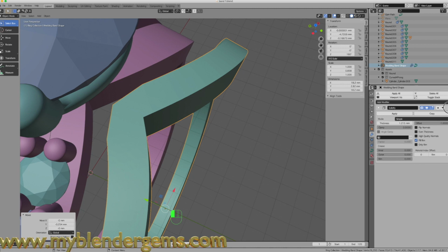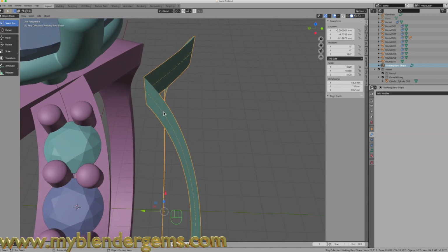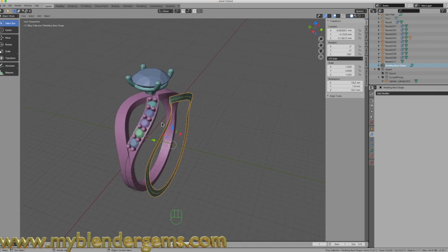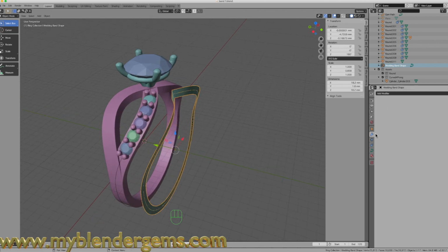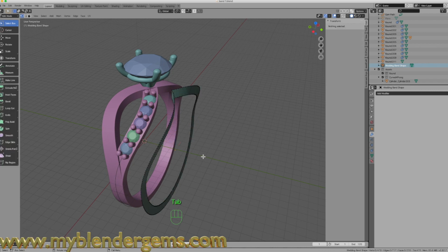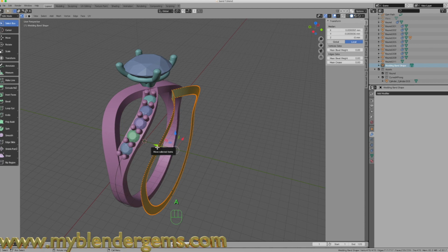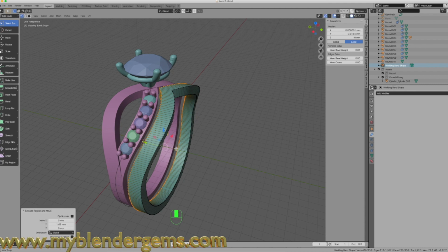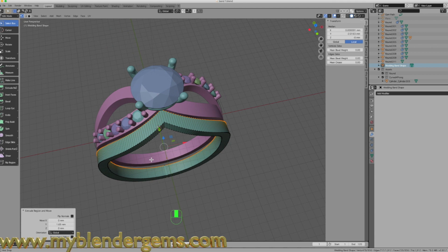If you didn't want to use the solidify modifier, we could convert this to a mesh and also just extrude this to the left or right, and that would be done like this. We take this model, and we don't have any modifiers on it, but we want to convert this over to a mesh. So if I do that, I go into edit mode, hit A so that everything is selected, and now I can hit extrude and then Y, and then I can bring that over just like so to make that simple design like that. And I think I'll do that on this particular model.